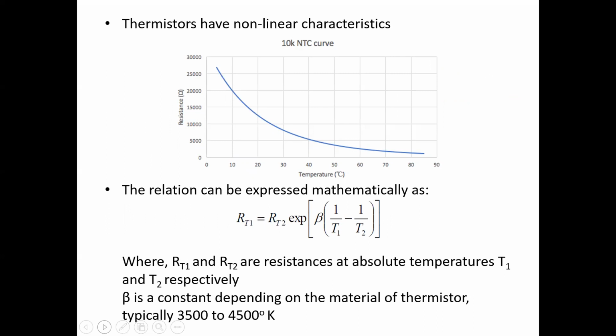So here is a typical graph of a negative temperature coefficient thermistor. You can see that the temperature is not varying in a wide range. Within a smaller range, the change in resistance is very significant, because from the y-axis you can consider the jump from one point to another, and you can see that the change in resistance is really high compared to the change in temperature.